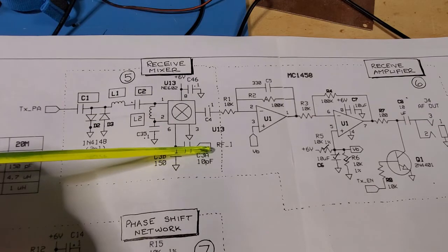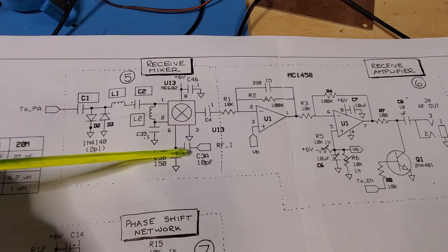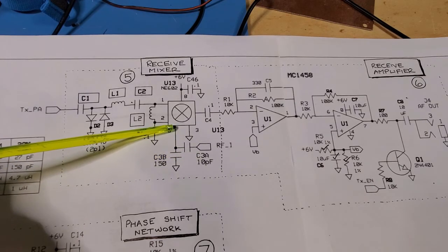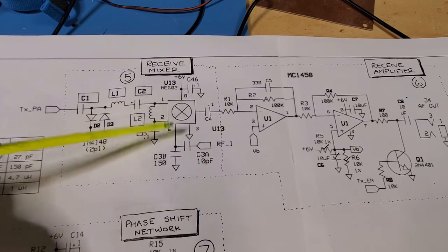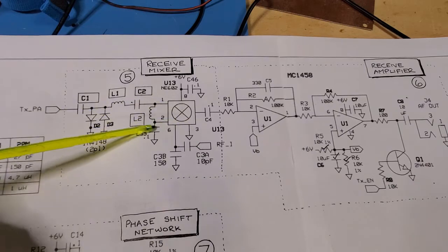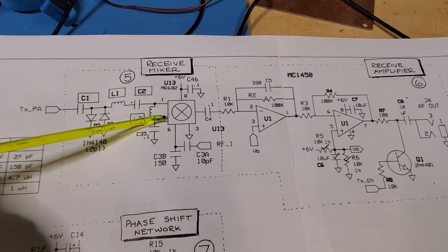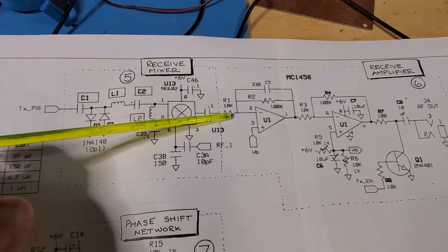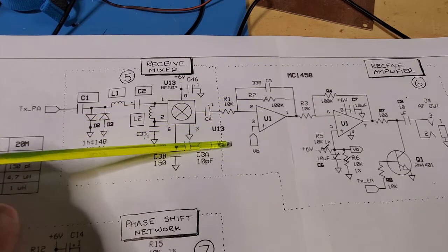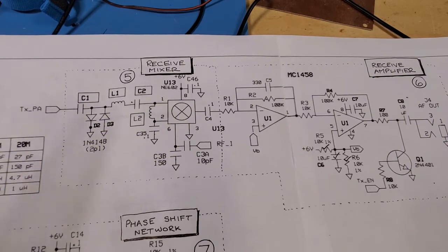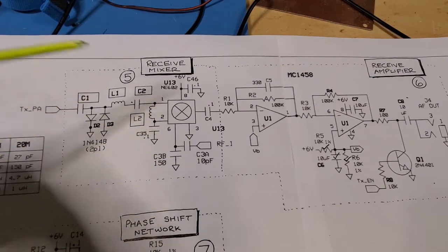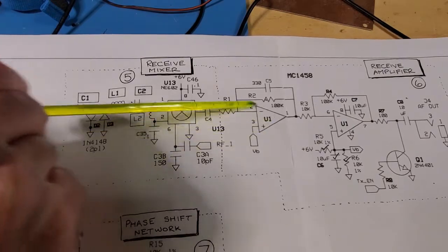There is also the RF signal generated by the SI5351 and the D-type flip-flops, which gets presented here at the oscillator pin of the NE602, and those two signals get mixed together. This is a direct conversion style radio, where the LO frequency is the same as the receive frequency that you want. So the mixed product coming out of here will be simply this frequency plus or minus this frequency. Further, that frequency will be at the audio baseband.